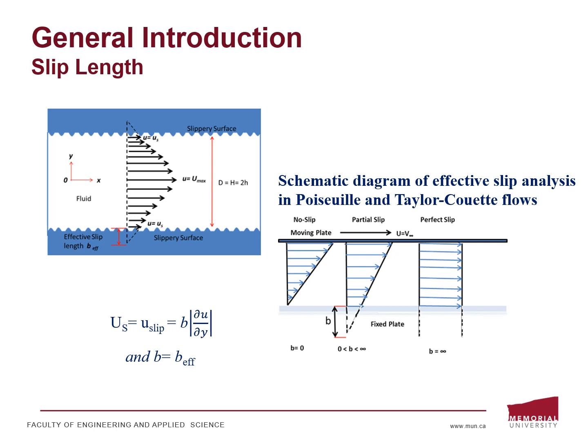The slip length can be interpreted as the depth into the boundary at which the velocity profile can be extrapolated to zero. The slip velocity is directly proportional to the magnitude of the shear rate experienced by the fluid at the wall, as proposed by Navier's slip model, which says the slip velocity equals the slip length times the velocity gradient.